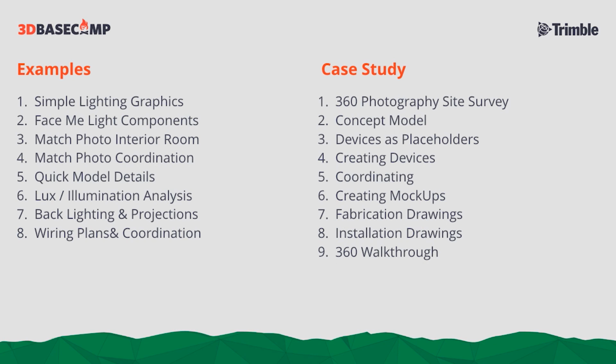So some of those real quick, I'm going to show you how to do simple lighting graphics, how to just really convey lighting quickly, how to use FaceMe Components, how to use Match Photo. Anybody use Match Photo in SketchUp? Awesome. But then more importantly and more recently, I do a lot more from SketchUp to Layout. I used to never use Layout 3-4 years ago, and now it's pretty much every project where I'm annotating or documenting something in Layout. So I'll show you how to do quick model details.